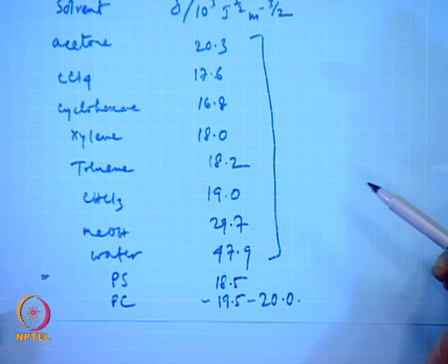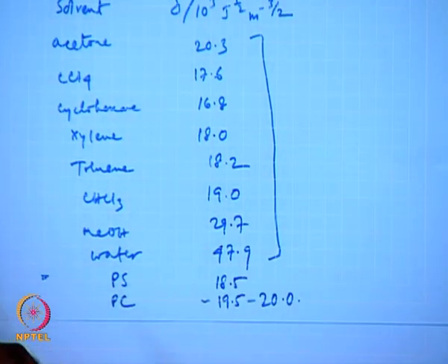in medical devices like syringes and some other medical components, in most cases before use they are sterilized by applying some rectified spirit which contains alcohol. Now, if you know the solubility parameter of that alcohol, then you can narrow down the choices of your polymer to those which will not be soluble in that alcohol used for wiping or sterilizing the equipment.